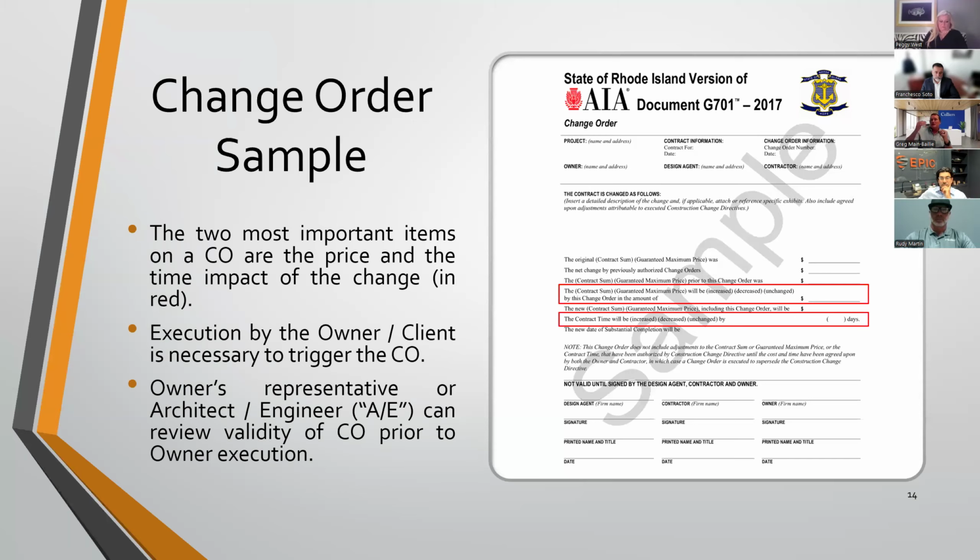unit-based price quantifications. And Ben and I will have a sit down and we'll say, all right, how many square feet of full depth work do you feel that we have around this building? And we'll do a quantitative takeoff, as an example of 100 balconies at 100 square feet a balcony.